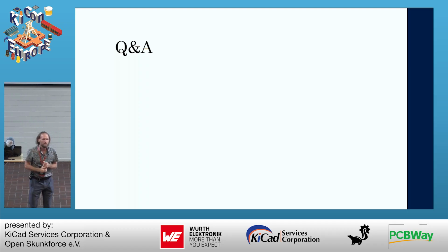I've been doing custom DRC rules where I just fill out a spreadsheet, save it to a CSV, and have a Python script that generates the rules for me. Okay, I didn't get your question, Paul. The question is, have you looked into automating the rule generation for this? I think that would have to be an external tool. You could write a script, but I don't know of any tool that does it.